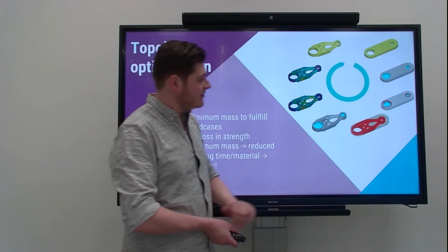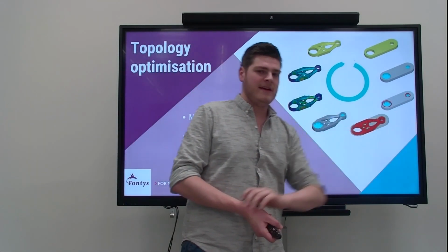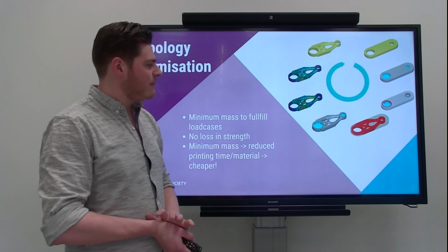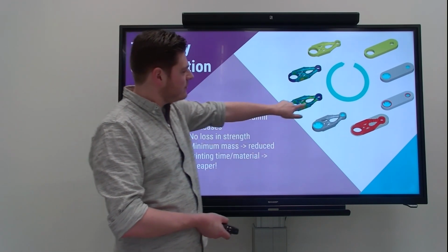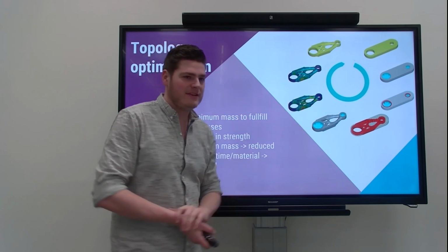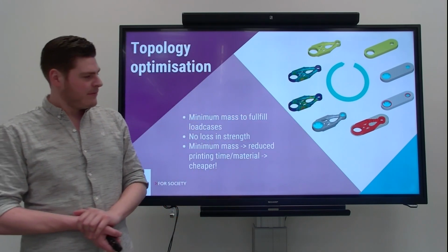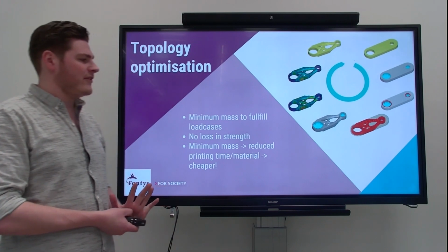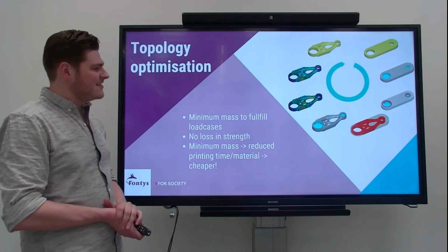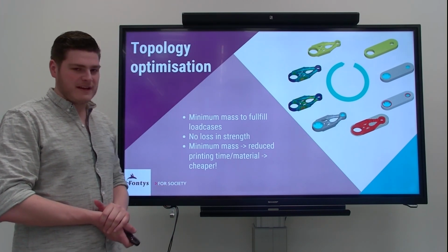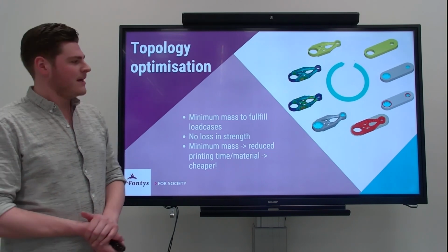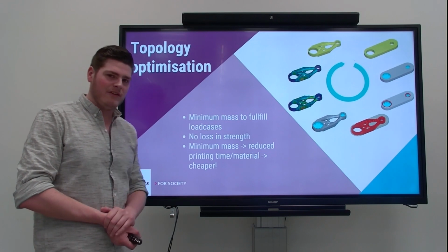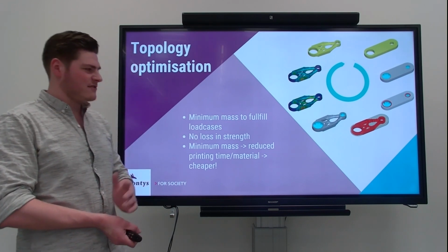I also define a force in one of these holes, and with that it starts calculating what is the minimum material that I need to still withstand all those stresses that will be put into that material. So most of my material is only put under a tensile stress, and that will result in a much stronger connection. Most of the time, a product will fail under the forces of shear stress.